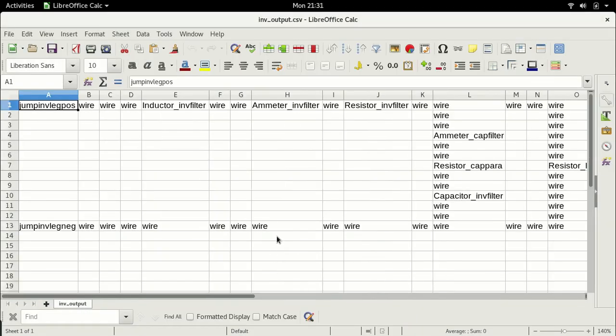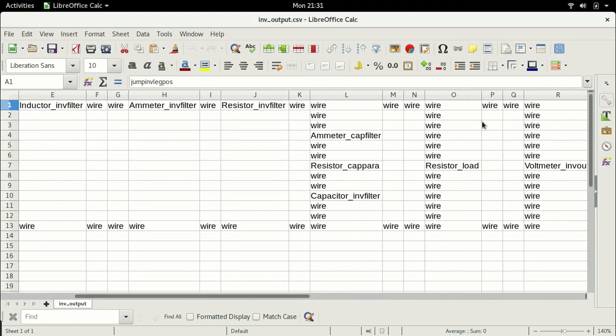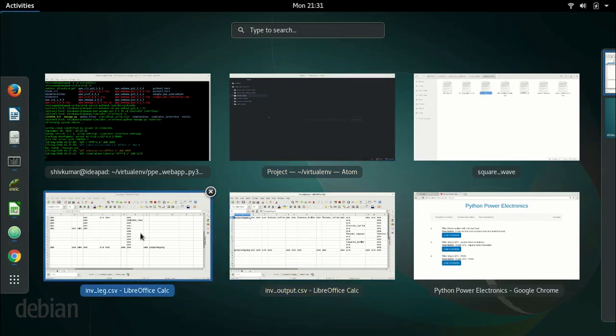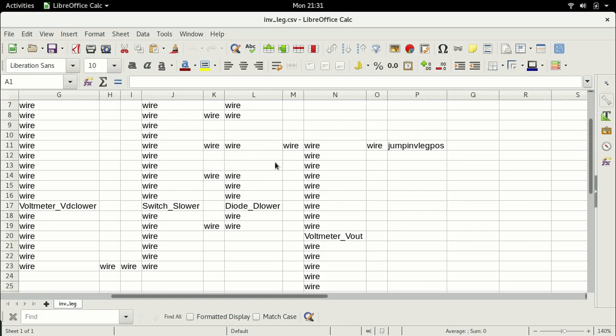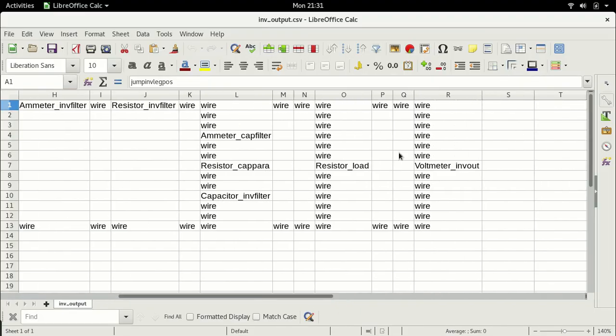And what we have here is a filter and the same resistor and voltage output. So we are measuring the voltage at two places. We are measuring the voltage directly at the switched output voltage of the inverter leg, and we are measuring the output that is finally available after all this.